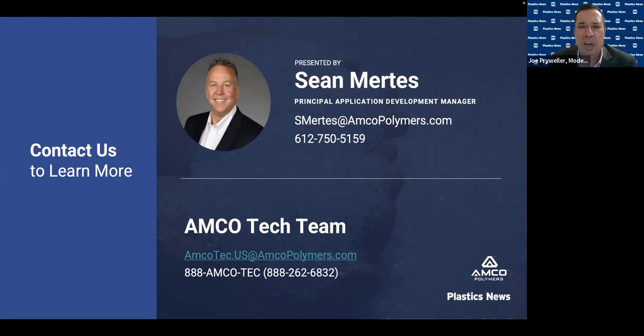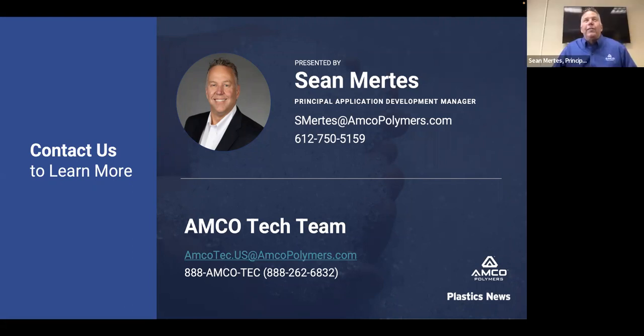Great. A few more questions here. Is there a good calculation based on material parameters to determine a cycle time for quoting? That's exactly what I'm working on. That's one of the things that I'd love to partner with somebody on, because right now we're using estimations. Let's say that I'm running a polycarbonate at 515 degrees or 525 degrees. And I know that I can kick it out at 300 degrees. That means I have to pull out 225 degrees. How fast can I pull that out? Now, once again, that has an effect of mold steel temperature, wall thickness, how quickly I can pull that heat out.